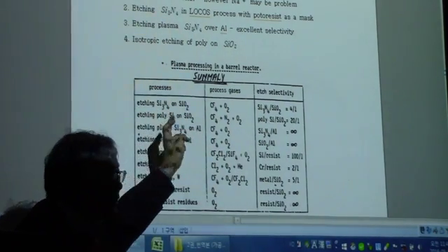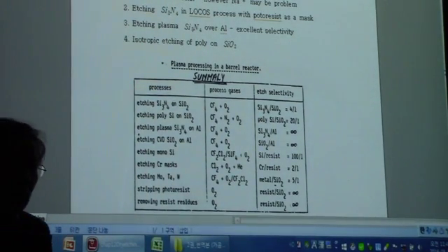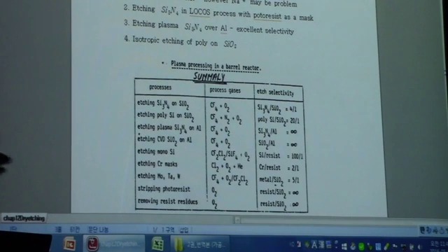In the local oxidation, LOCOS process, you form a base oxide, 300 angstrom of base oxide first, and then you deposit the silicon nitride on top at 1100 angstrom, right? And then you etch locally, and then you do the oxidation to form a bird's beak and things.